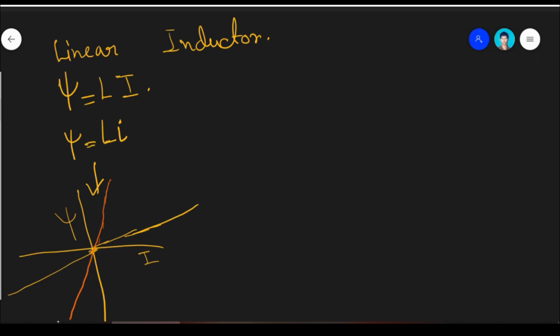However, what we can observe for this psi-I, if we take an iron core inductor, is that if we linearly increase our current from 0 to some value, and the current level exceeds a certain value, our flux also gets saturated.